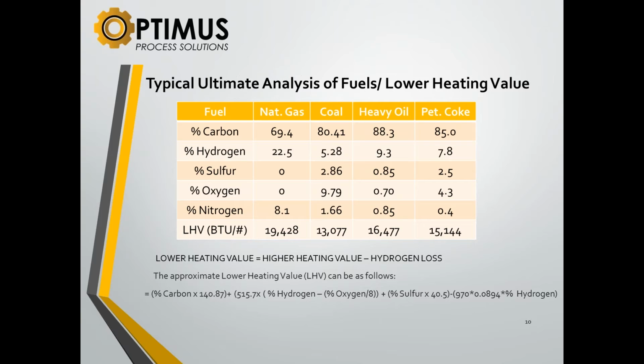Due to the fact that you have these particles being burnt with coal and pet coke, they generally give you a much more luminous flame, which effectively gives you more radiation heat transfer to your bed of material in your kiln. Right, so it's a brighter flame. It's a brighter flame, yes.